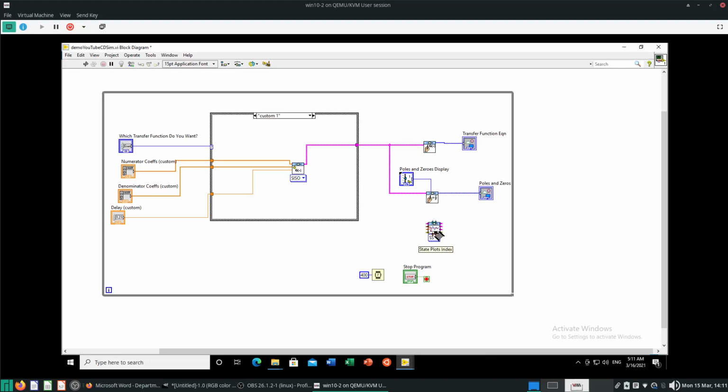So there are lots of inputs and outputs here. Let's look for the one saying state space model or transfer function model. You can select automatic, and that will detect the kind of model you have, whether it's in state space form or transfer function form. Using automatic mode will enable you to just put in any of those. By default it's in SS or state space, but once you draw the wire over to the state space model, it automatically becomes a transfer function model.